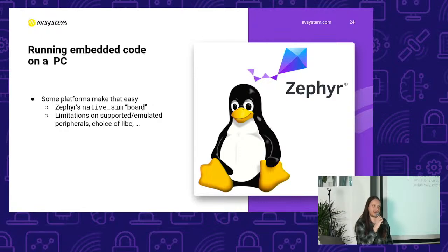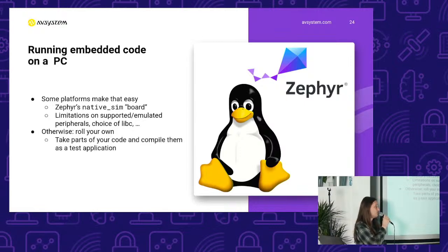Of course, you cannot test your drivers there. You may be limited in the choice of libc to the native libc of your system, but still this is your embedded code running on your computer. If you don't use Zephyr, then you probably need to roll your own, like you can just take parts of your code and compile it as a separate application.